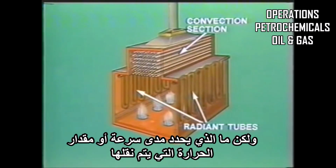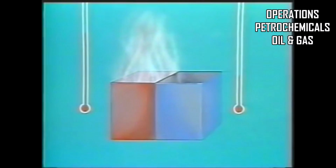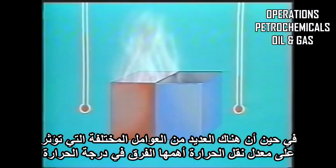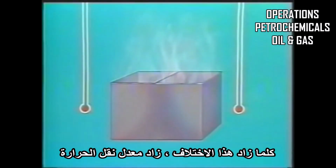But what determines how fast or how much heat is transferred? While there are several different factors that affect the rate of heat transfer, the most important one is temperature difference. In order for heat transfer to occur, there must be a temperature difference between two substances. The greater this difference is, the greater the rate of heat transfer.